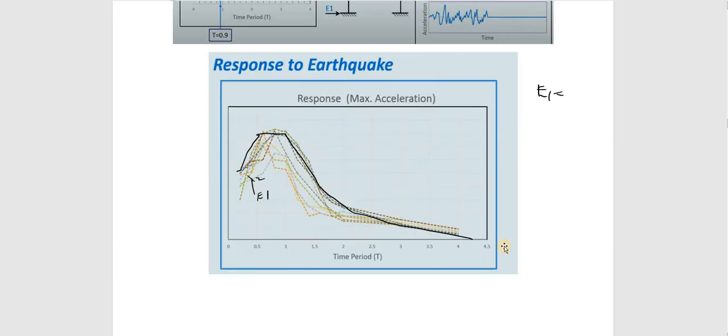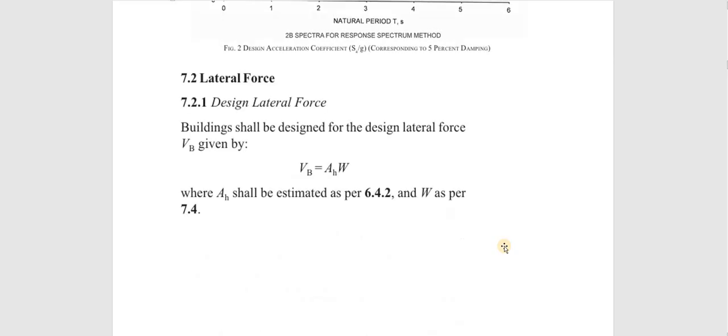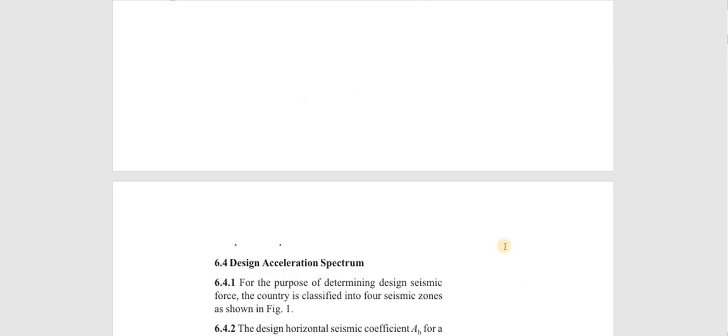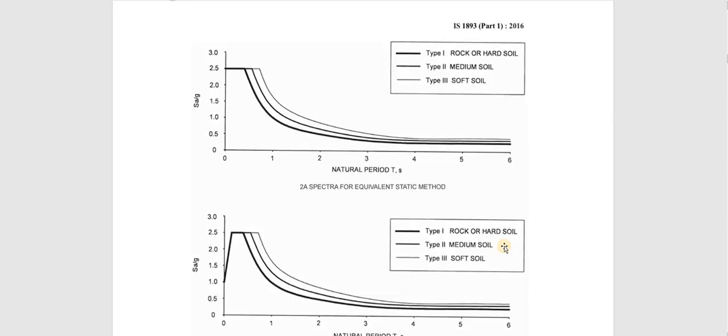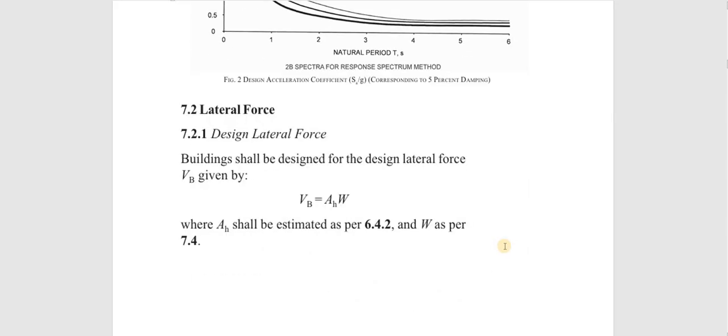Now, why have we found these response spectrums and why are we using them? The reason is that our main aim in earthquake or dynamic analysis is to find the force acting on a building, because we cannot calculate the earthquake. Earthquake is just a horizontal motion, and in dynamic analysis our aim is mainly to find the lateral force. For that only we are using all the equations.